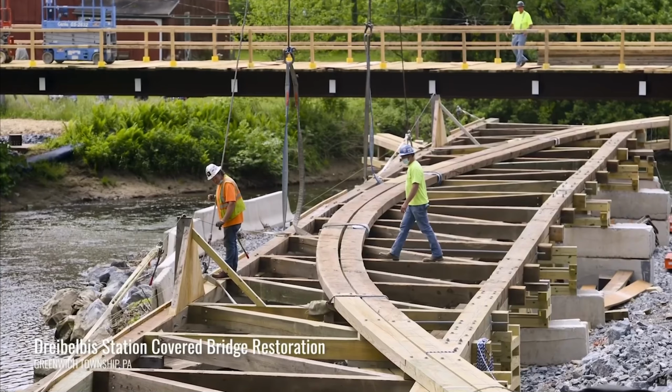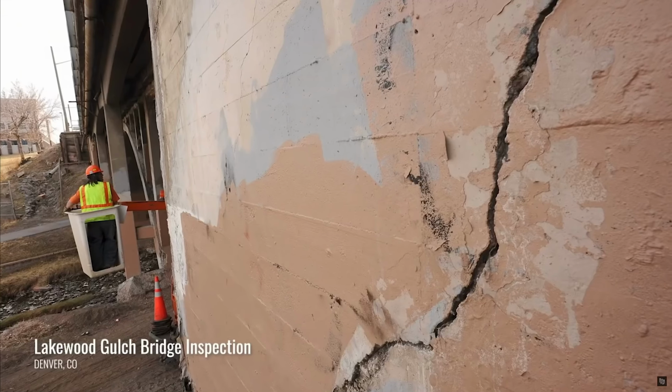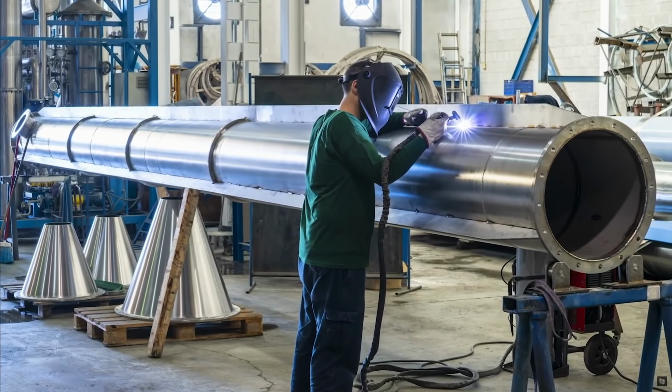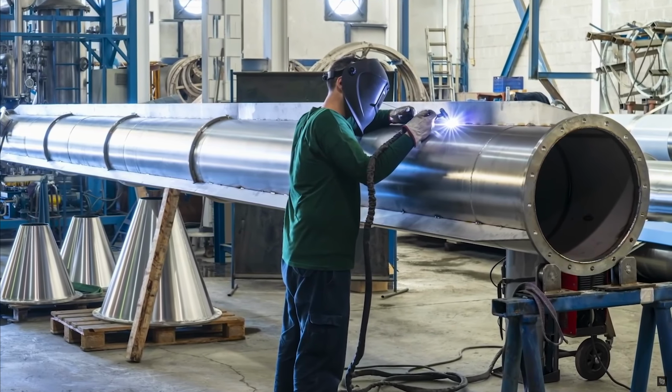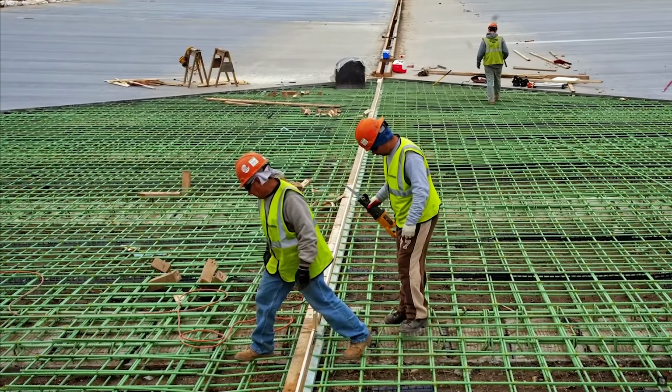There needs to be perhaps some modifications, removal of the concrete that has spalled off or deteriorated or crumbled and replaced with something more durable, such as weather protected steel, which we have, or epoxy coated deck. And so there are rehabilitation efforts that can just as well reduce or restore the ability of the bridge as opposed to just tearing it down.